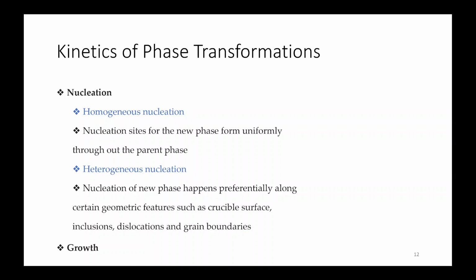For example, some silica particles are already present in solid state, and there is the mold wall that will act as a different phase that is present there. So it will find some supercooling there, so it will go and nucleate there. So whatever phase is forming can be a single phase as well. It can be pearlite as well, which is a phase mixture.